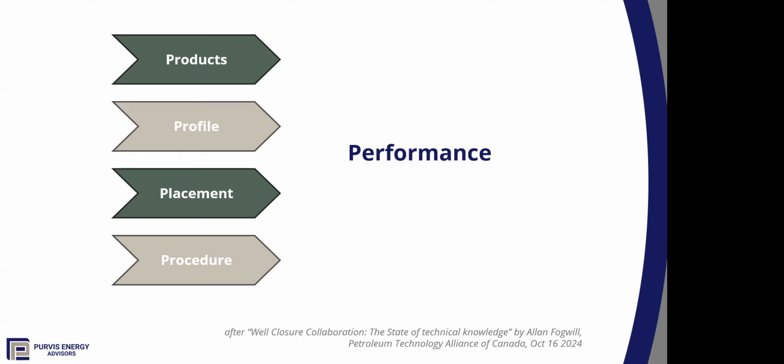We can look at seeps in the few locations, the concentrated locations where they exist. We can look at the variability of seeps, and we know, at least in some places, they vary with the tides. We can also look at the analog of leaks from landfills, which vary with barometric pressure. And there are probably some dynamics like that that affect wells. We need to understand those in the long term. Because if we can understand the nature of the flow, how it varies in the short term, how it changes in the long term, then we can better understand the failures, and then we can protect against those.